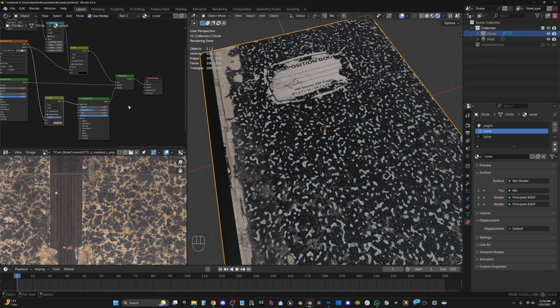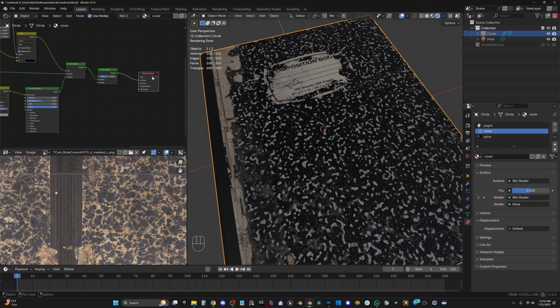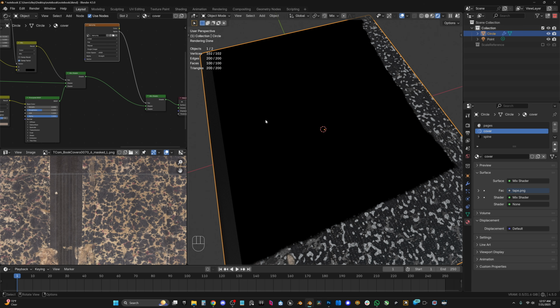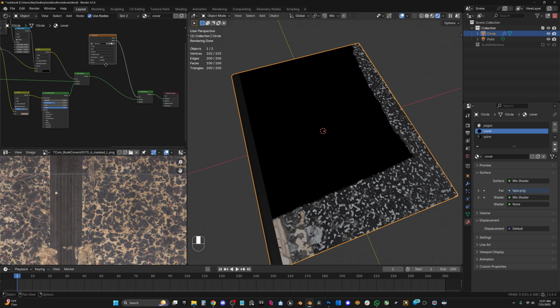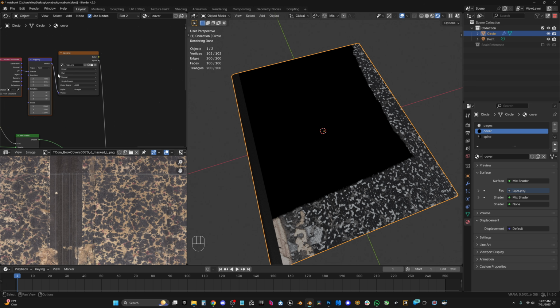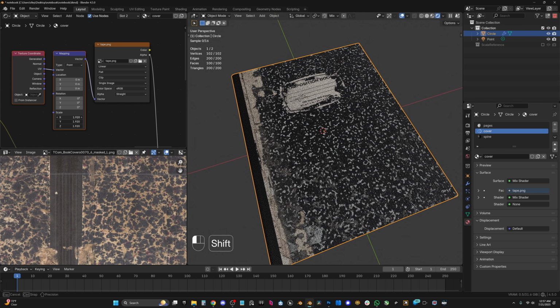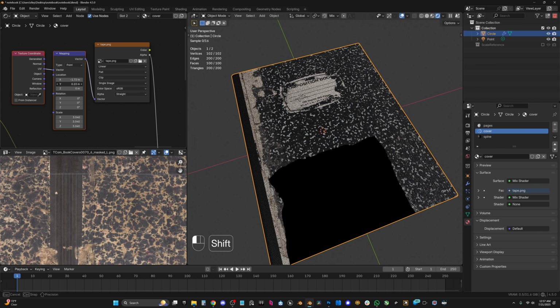Just export. Let's just do another mix shader. I know there are decal plugins. I try to go as vanilla Blender as I can for my tutorials, just so that people can follow along without buying stuff. Every now and then there is something I just really recommend that you buy, like UV Pack Master. That's great for UVs. Let's change this, same as the other ones. Let's change it to clip so we don't repeat here. And we're gonna really have to play with this scale. And again, I am just going to eyeball the proper dimensions.